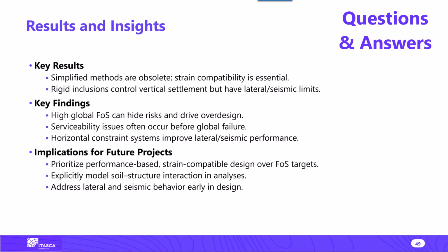If you're using factored properties, you have to use factored properties for both. At the end of the day, the integration of the domain that I'm using in FLAC 3D comes from a simple sectional analysis in which I have the concrete and the steel and determine the moment-curvature diagram like you would do for LPILE. So the response is the same.